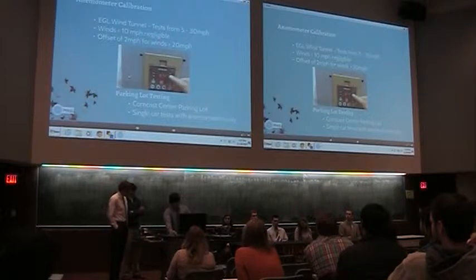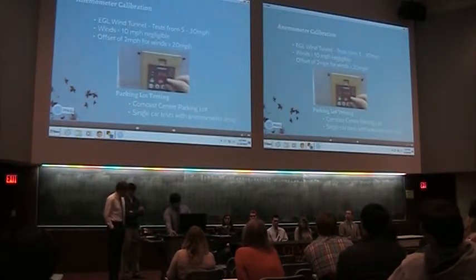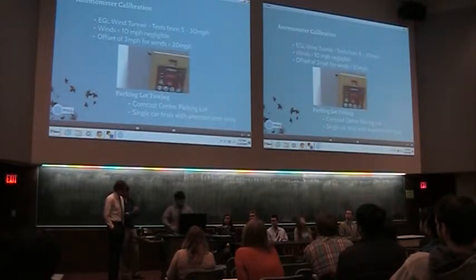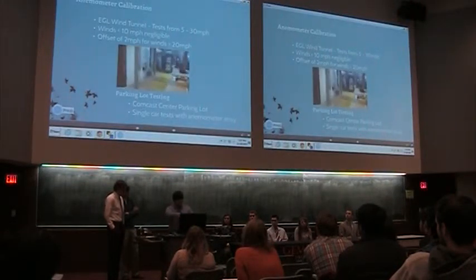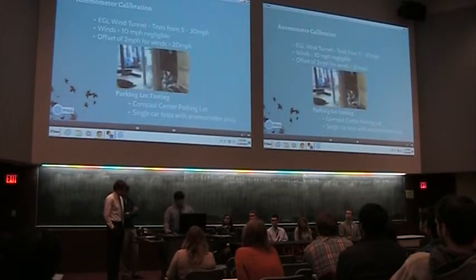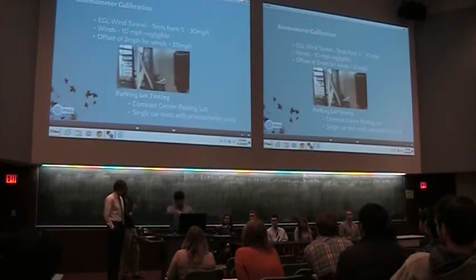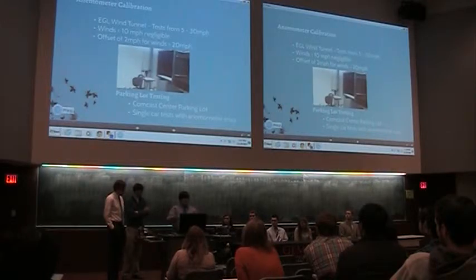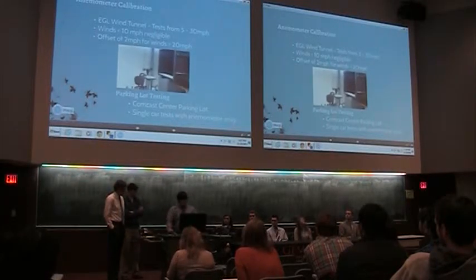Here's a little video showcasing how we went about this. So you would set the wind speed at the little box there, and then it would blow out that wind speed, and then we could basically test to see if our anemometers are accurate or not.